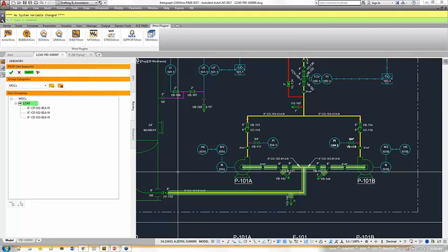So there would have to be a secondary tagging operation on an AutoCAD P&ID. That would be the busy work to support LINKWorx and give us the line number annotation. We are not reaching into an AutoCAD P&ID if we're using the Autodesk AutoCAD P&ID product. We have a unique tag that has to be placed on it.